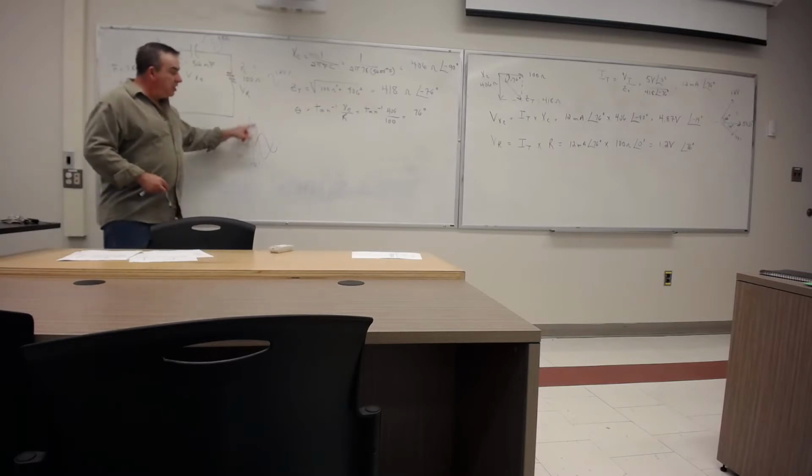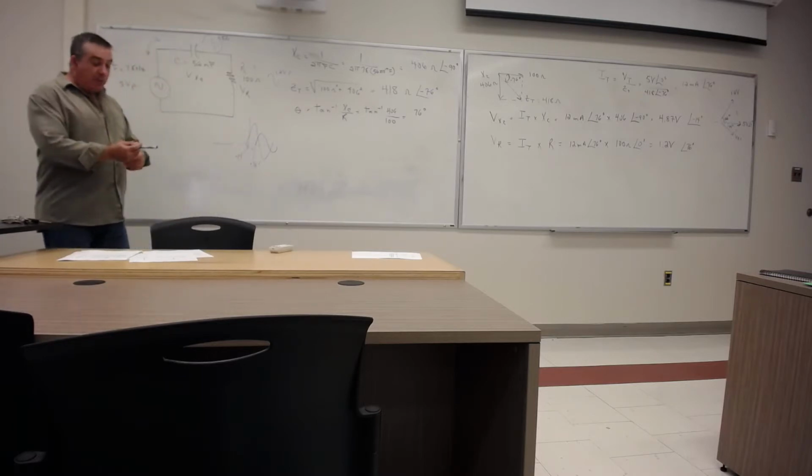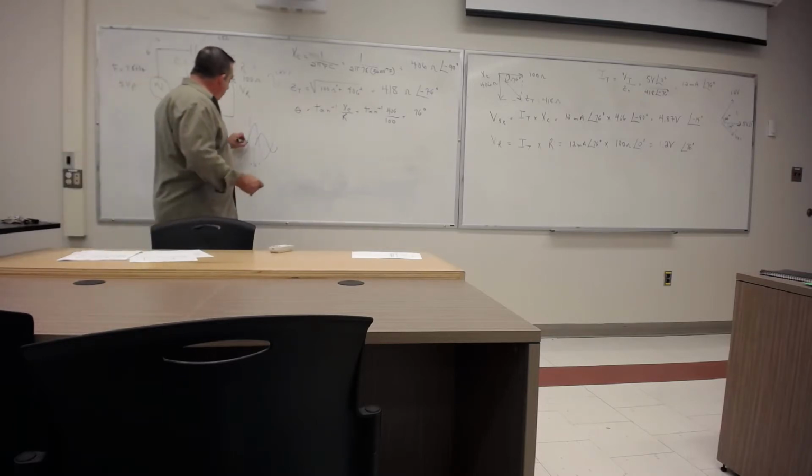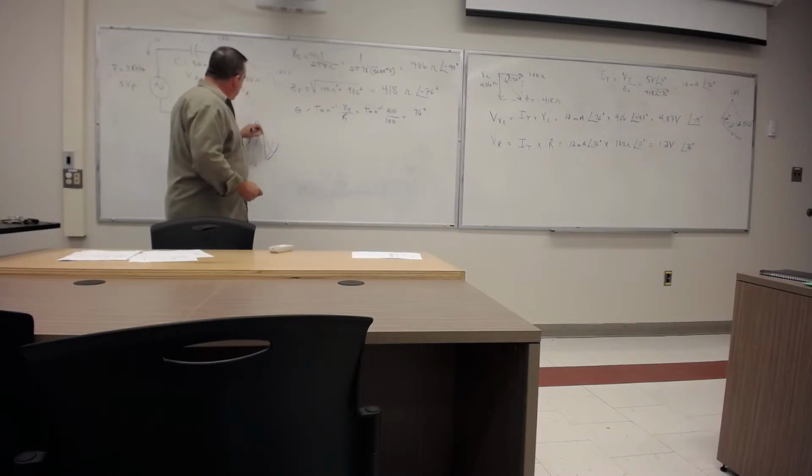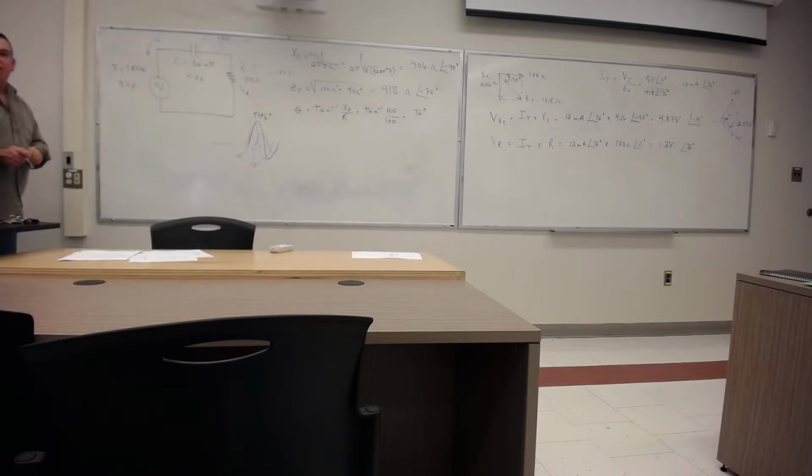If you took those things and put them in a summing amplifier, they would actually produce one wave at 0 degrees, 5 volts peak. That's what would happen. Those 2 sine waves, if you could add them together, you can do it with your scope. Put one on channel 1, one on channel 2, put add, and they add up to be one wave at 5 volts.